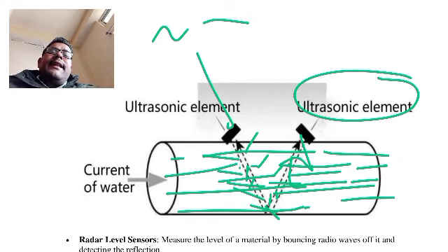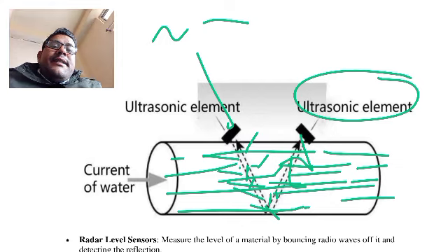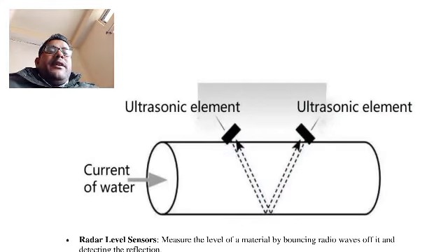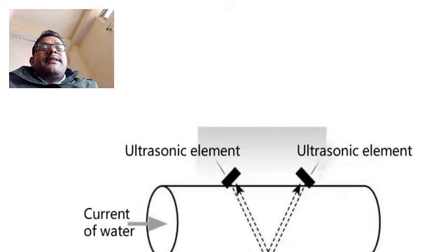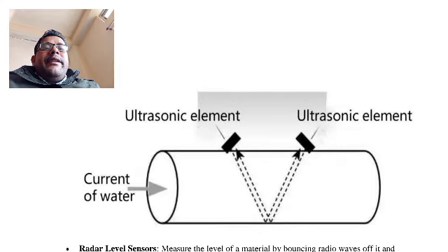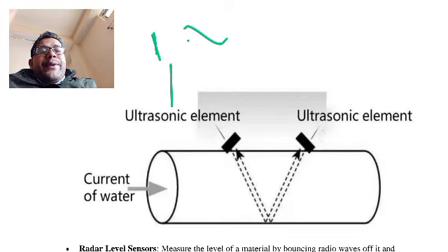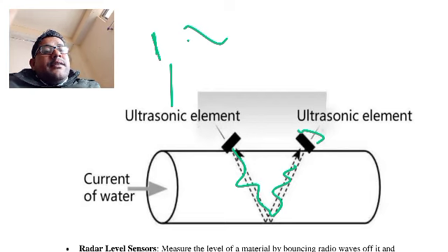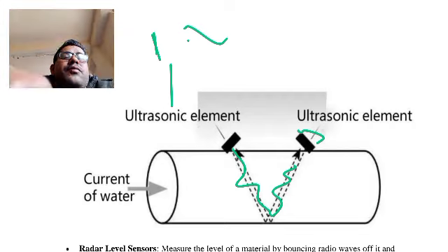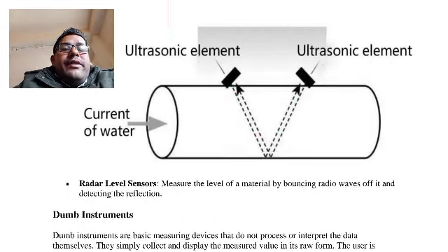This instrument can receive the signal and transmit the signals, so it has both functions. Generally a piezoelectric sensor is used. At one time it can act as a receiver, and at another time as a transmitter. Here piezoelectric material is used. When a force is applied from outside, it generates waves in a burst, and when the wave strikes the material again, it creates a voltage, because it is a piezoelectric material. In this way we can use this instrument.